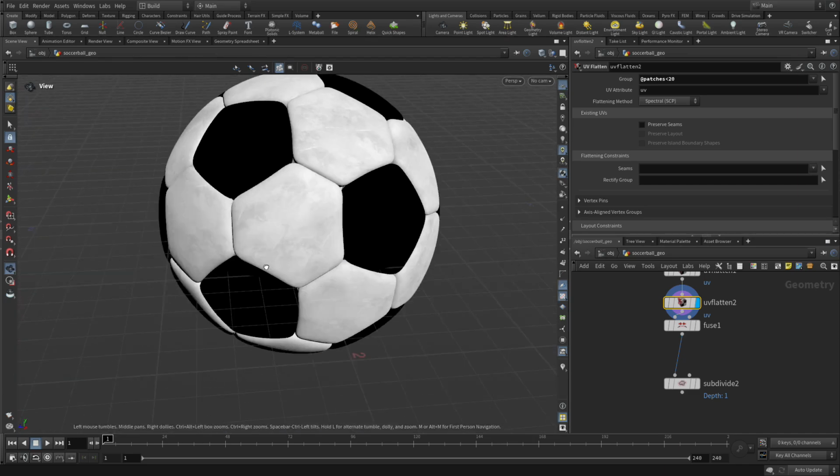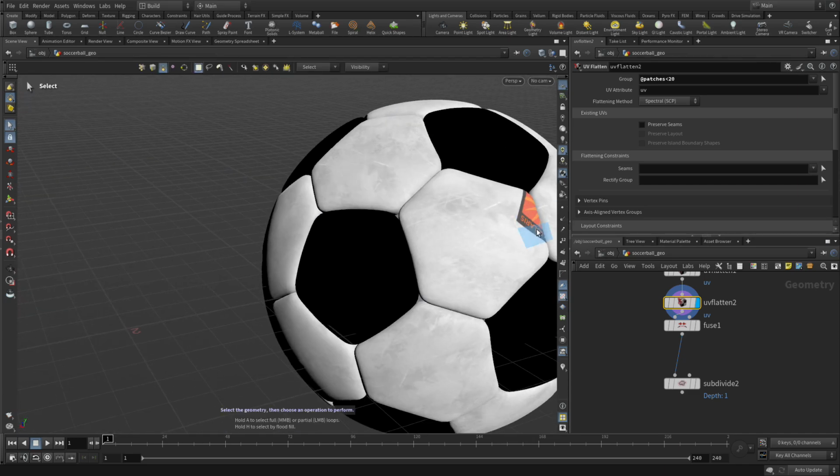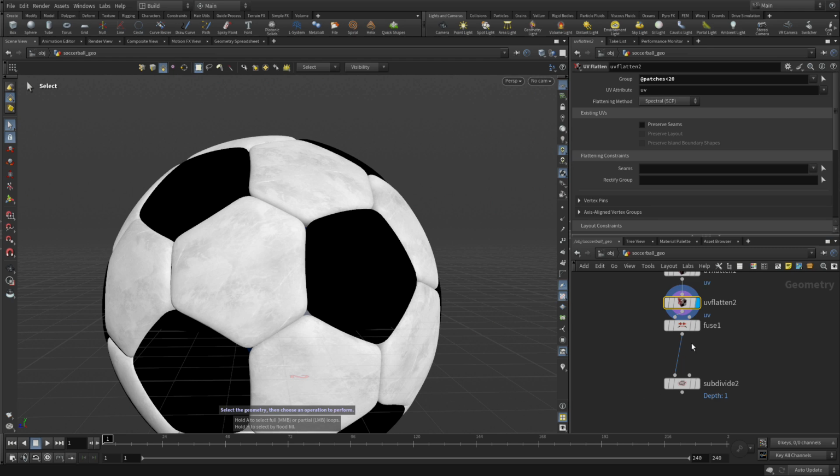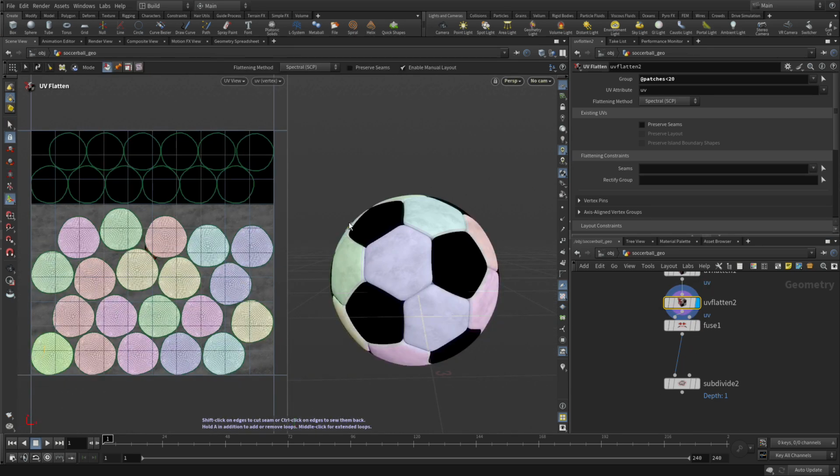So we see the textures now. Right now that piece is over there. That's not particularly what we want, but it does show you what's possible. Now if we go back to the handle tool, we'll go back into this, which is what we want to work with. So what we want to do is click on the pin vertice option here, and then we're going to shift click on that point right there, and that will allow us to get one of these sections.